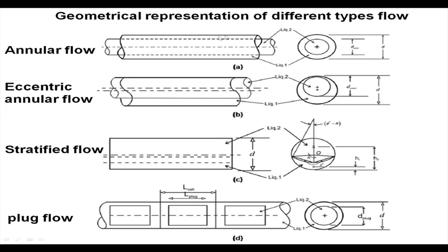On the other hand, for higher velocity of the other phase, the organic phase, we have annular flow pattern. So, we have assumed both situations. We have developed the model for a concentric core as well as for an eccentric core. In the eccentric core, we have assumed that a very thin liquid film is flowing on the top wall, such that they are almost touching, but yet there is going to be some interfacial shear between the organic and the water phase throughout.